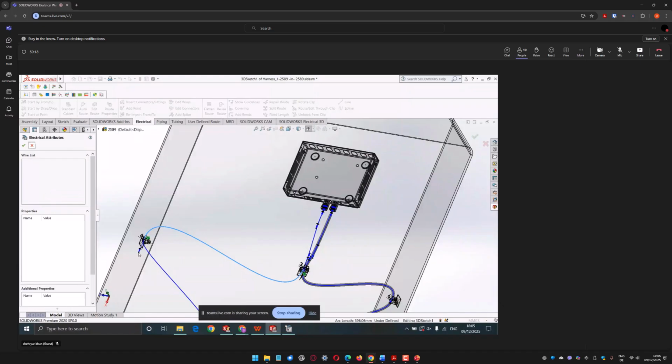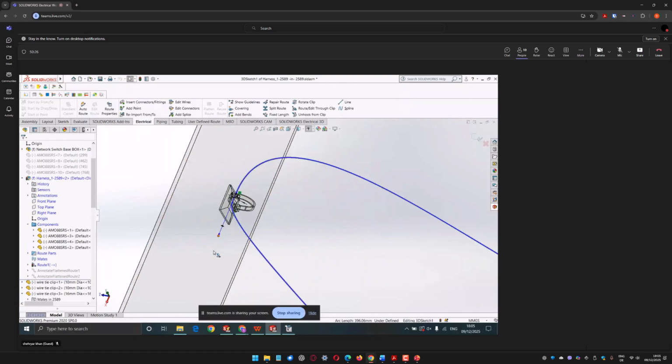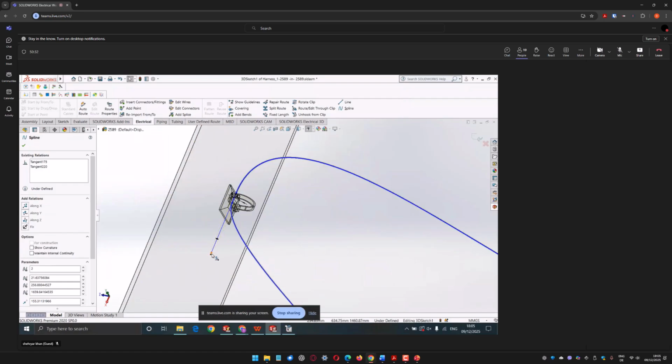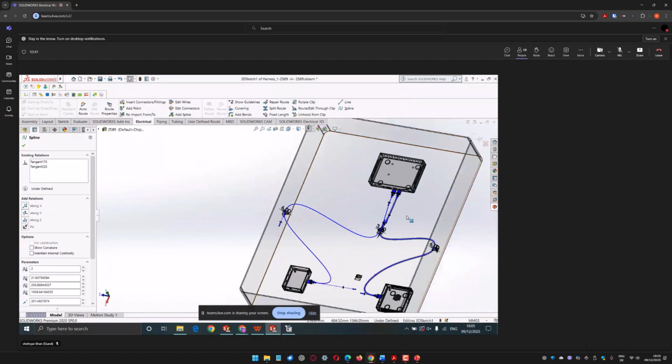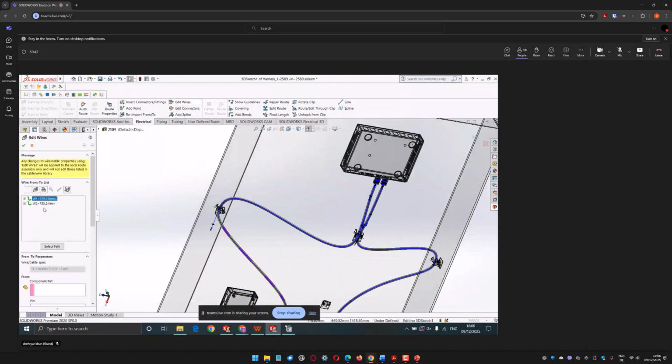I'll close it and then check whether my bend radius is correct or any issues with that. I think this is too close. I'll just put a bit more bend to it. Yeah. Now what will happen? Still this is an issue. I'll go to my edit wires and check whether my wires are correct. Everything is passing through the cables, W1, and so W1 was incorrect.